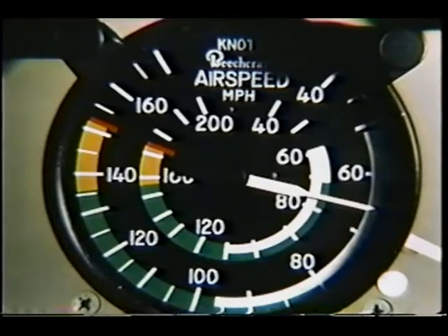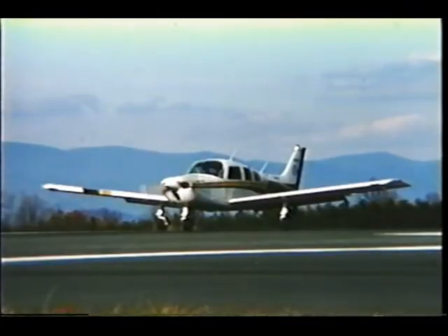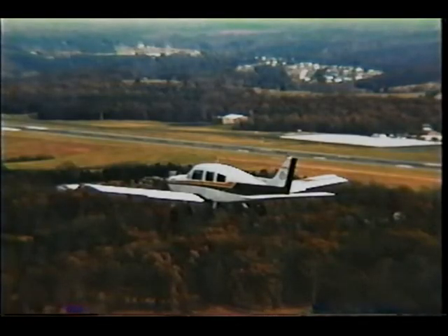Mastering airspeed control is the most important factor in achieving landing precision. Precise control of your airspeed during the landing phase is the key to touching down and stopping the airplane where you want it, and not landing long. Achieving precise control of your landing speed begins in the traffic pattern. It begins with the concept of a stabilized approach, something we discussed in detail in Part 1.